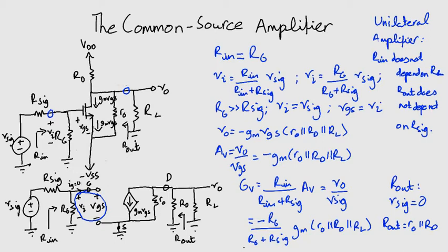I have included Rn, Vi, Gm, VGS, and Rout, and also R0. Now remember that before we start our small signal analysis, we are to open our current sources and short our voltage sources. However, here I have left the voltage sources as they are, the DC voltage sources that is, and removed the capacitors and replaced them with short circuits and opened the only current source that was present. This analysis directly on the circuit saves a lot of time.